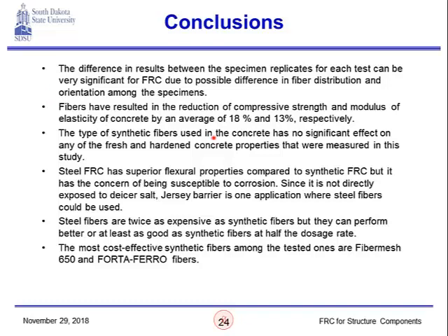The type of synthetic fibers used in the concrete has no significant effect on any of the fresh and hardened concrete properties that were measured in this study. As we saw in all of the properties, regardless of the fiber type, the FRC really behaved similar to one another.